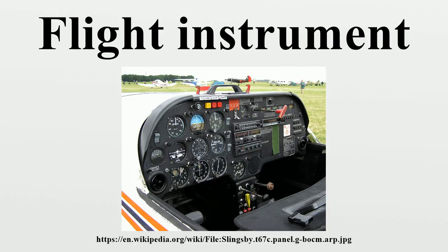Layout. Most aircraft are equipped with a standard set of flight instruments which give the pilot information about the aircraft's attitude, airspeed, and altitude. T arrangement. Most aircraft built since about 1953 have four of the flight instruments located in a standardized pattern called the T arrangement. The attitude indicator is in the top center, airspeed to the left, altimeter to the right, and heading indicator under the attitude indicator. The other two, turn coordinator and vertical speed, are usually found under the airspeed and altimeter, but are given more latitude in placement.